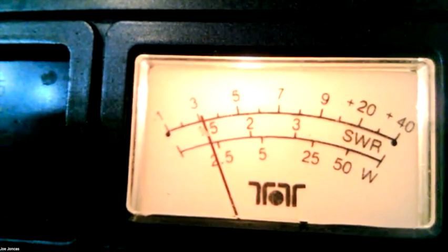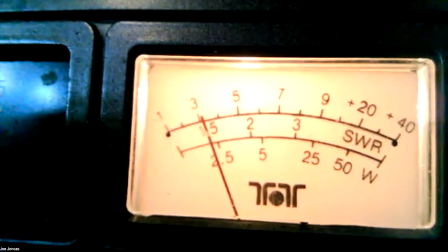Remember what's happening is you've got somebody across the United States sending out a radio signal, and it's going all the way across the United States, hitting your antenna and creating 50 microvolts, because the signal gets induced into the antenna, which creates a voltage that your radio is able to receive. But we're going to get into all that detail much later. Does everybody understand how their S meter works?